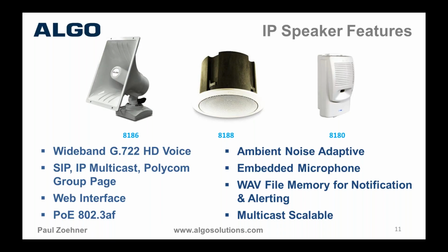And then you can go to any web browser and type that IP address into the address bar, and you will get to the web interface, and then through a password you can get to all of the configuration parameters for the device. Usually you want to give it the IP address of the SIP server, and you need to put in the credentials if it's going to have a SIP extension, the extension, and the password. All PoE, of course, AF.